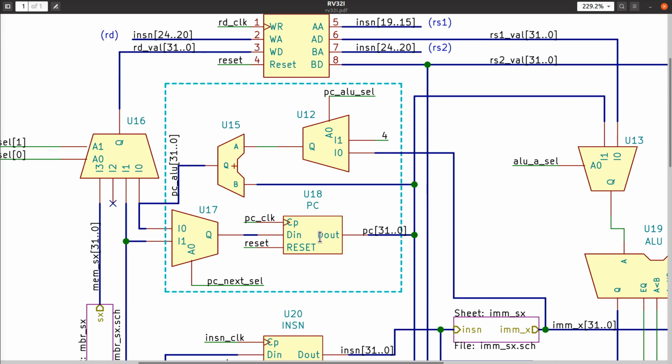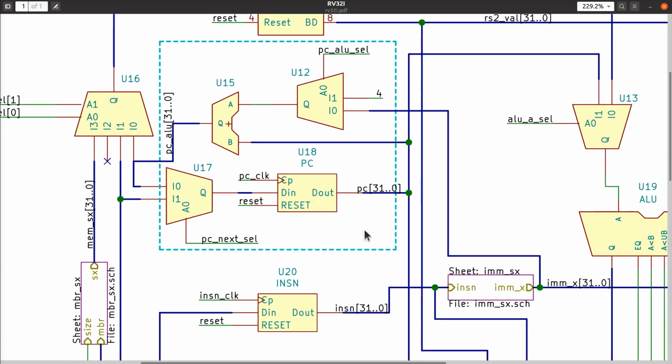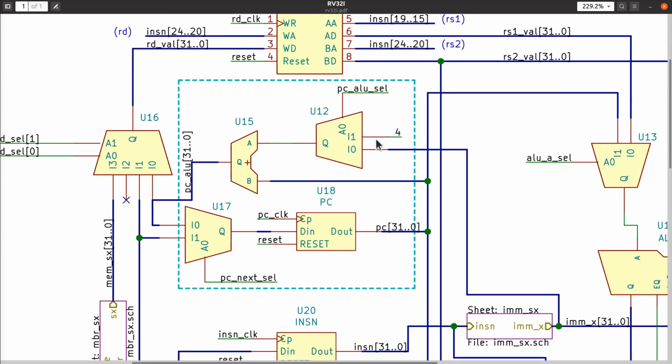And we can, in that case, use that to execute any number of instructions as long as there's no branching, okay? When there's branching involved, we need to do other things. Like, for example, maybe we need to add the current value of the immediate operand in the instruction to the program counter instead of just 4. That would allow you to branch to an address relative to the program counter. And as we saw before, the branch instructions and the jump instructions have program counter relative addressing.